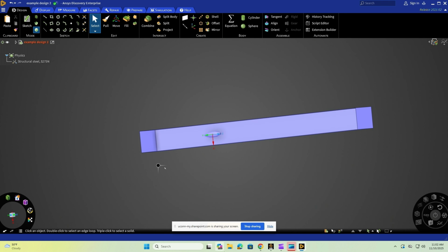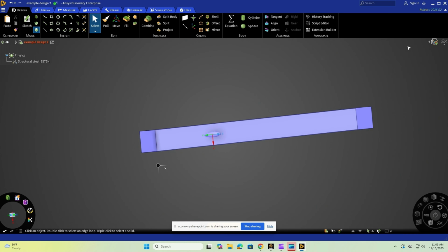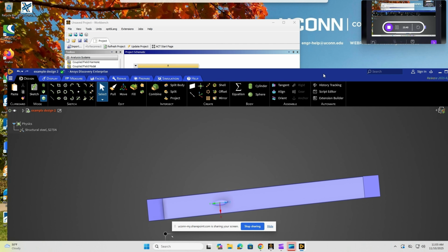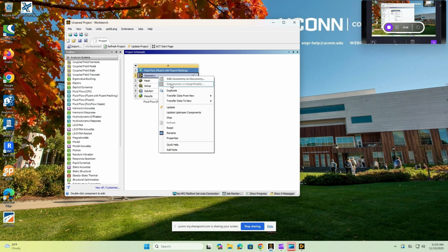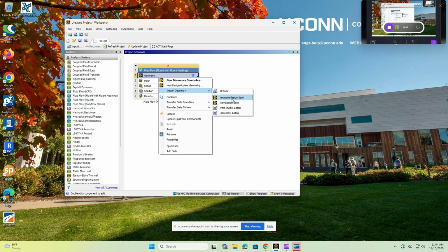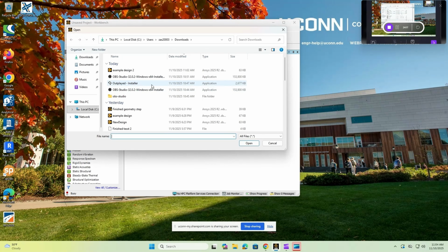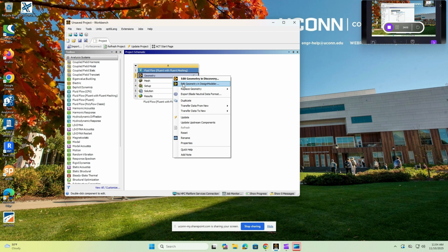This might not be the best way to do it. It's the way that worked the easiest for me. Make sure to save it to your device, and then what I've been doing is go into geometry. I reset, so I kind of delete what I just did, and then I open the other option. So I open design modeler geometry, okay? After I import what I just did right here, right? And then I open it in design modeler, okay?